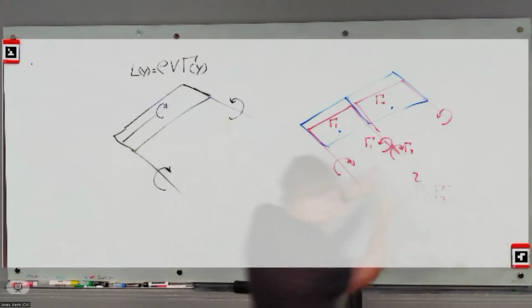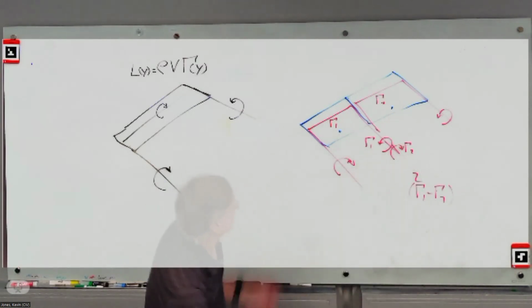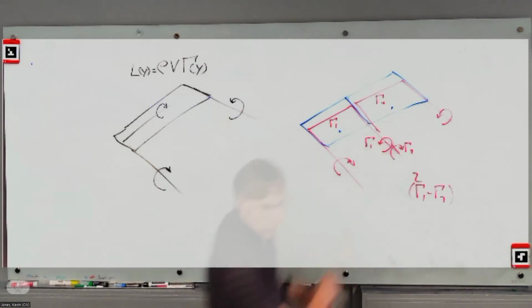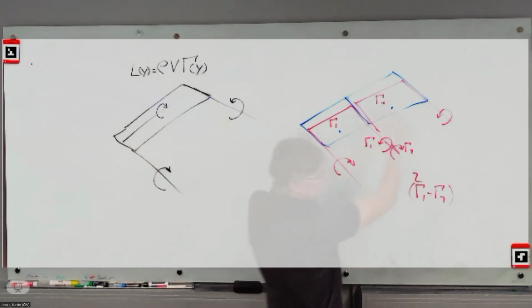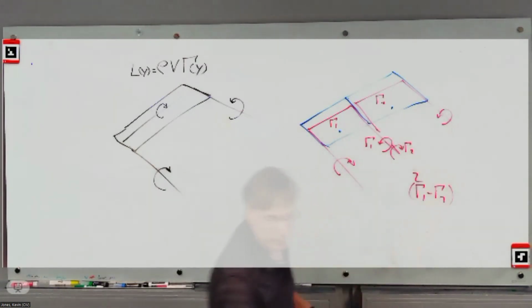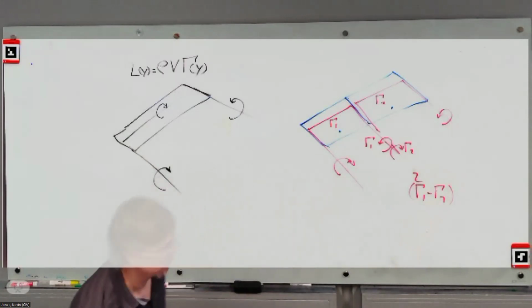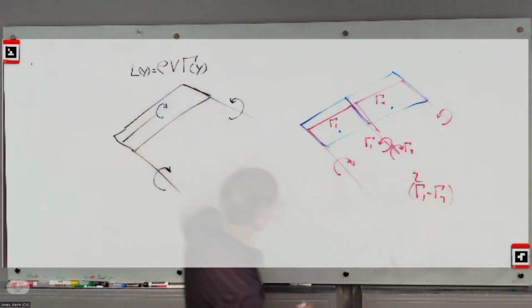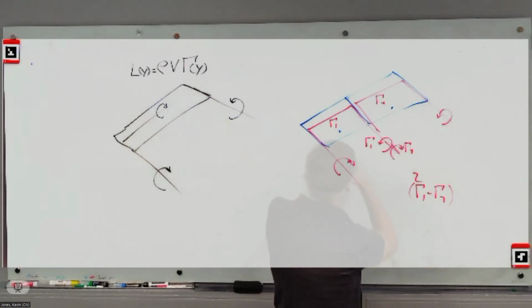That's really the delta gamma. So this is the discrete form. In real life, you would increase this to an infinite number of infinitesimal panels. This would be a continuous thing, and now you have a continuous shedding of vorticity out to the tip.